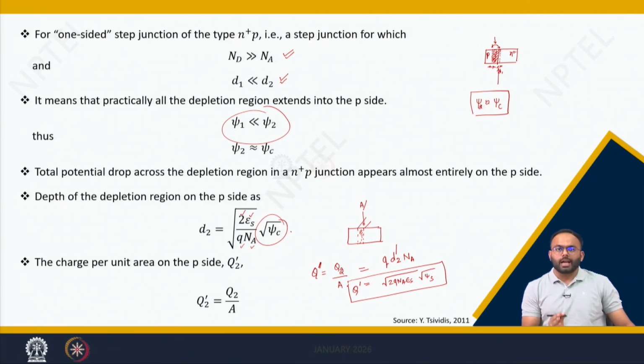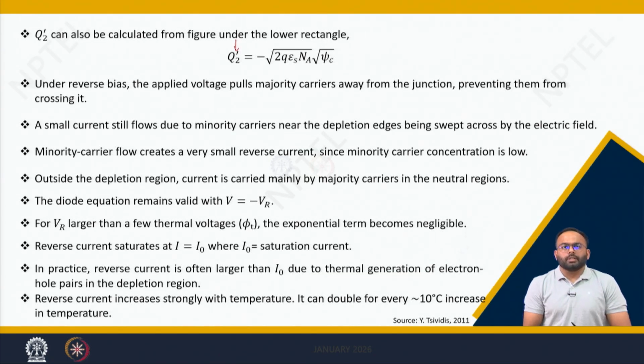It means at the lightly doped side. We are going to use this equation extensively when we talk about MOS transistor modeling. This equation tells us how the charge of the depletion region is related to the potential drop across the depletion region.